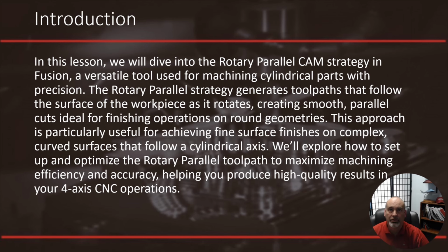In this lesson, we'll dive into the Rotary Parallel CAM strategy in Fusion, a versatile tool used for machining cylindrical parts with precision. The Rotary Parallel strategy generates toolpaths that follow the surface of the workpiece as it rotates, creating smooth, parallel cuts, ideal for finishing operations on round geometries. This approach is particularly useful for achieving fine surface finishes on complex curved surfaces that follow a cylindrical axis.